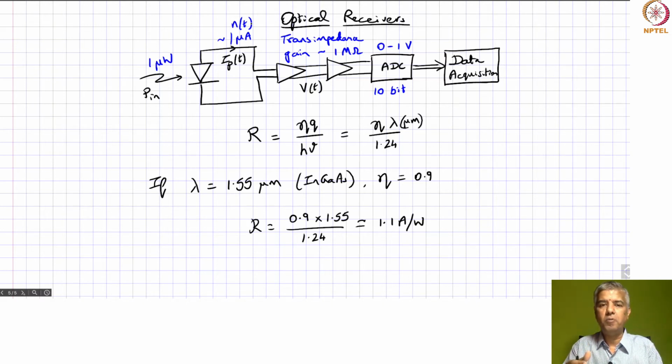Whenever you put an amplifier, you are boosting up the signal, but you are also boosting up the noise by the same level. So the signal to noise ratio can only degrade as it goes through all these amplifiers, because the amplifiers also add extra noise. Okay, so it will further degrade the signal to noise ratio that you have.